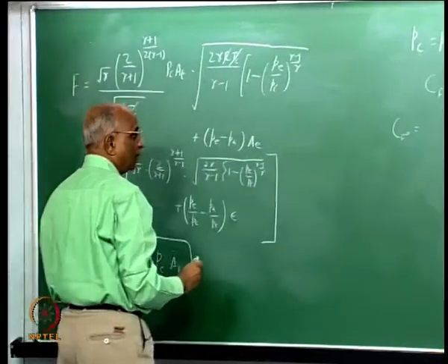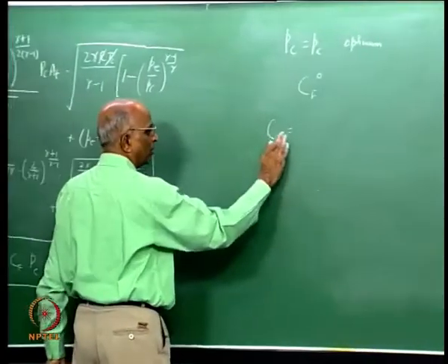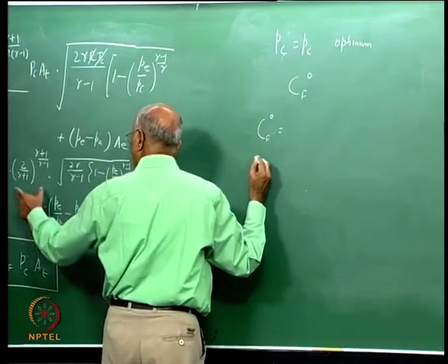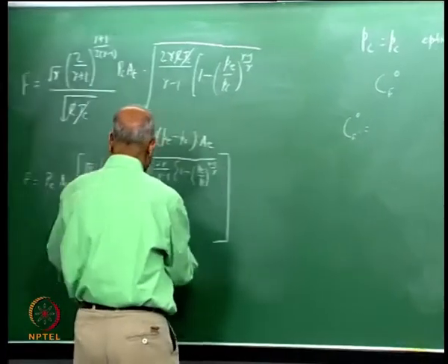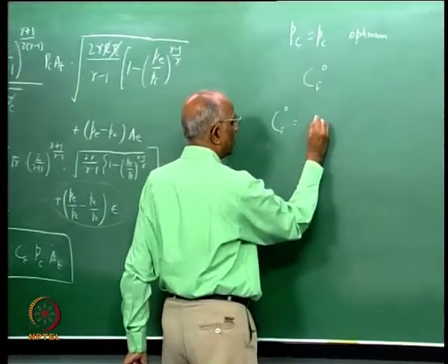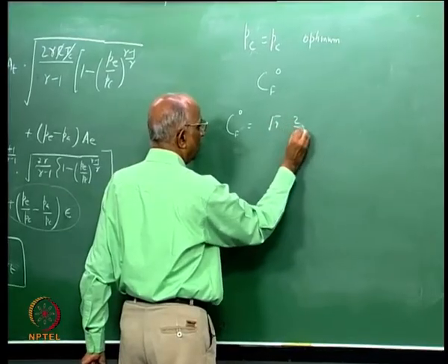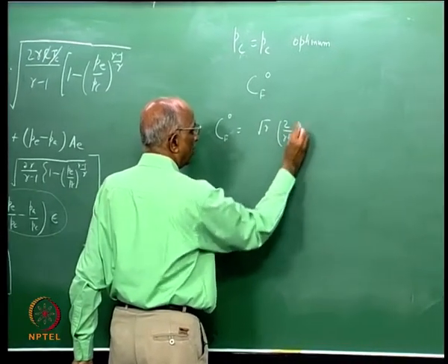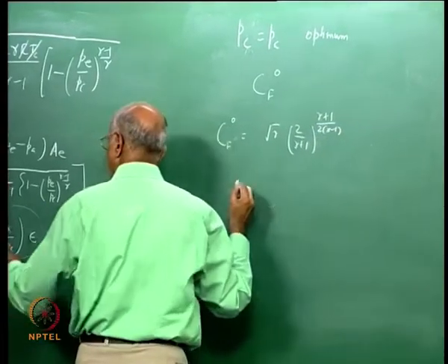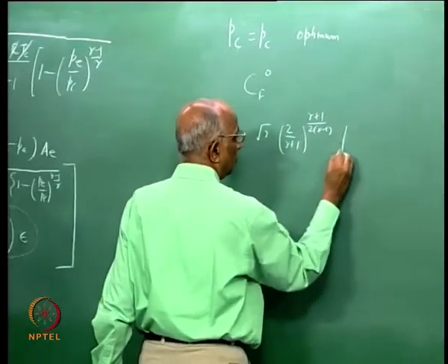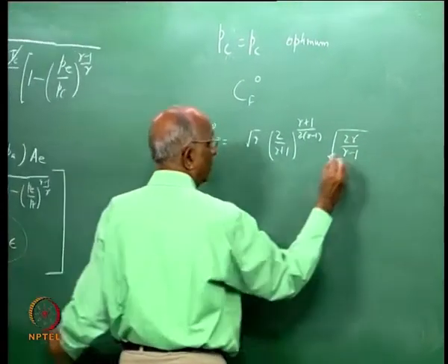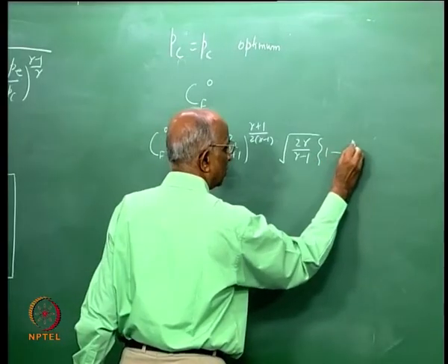I just write the whole expression other than this particular term which goes to 0, and I get Cf0 equal to under root gamma (2 over gamma plus 1) divided by (2 gamma minus 1) into under root 2 gamma by gamma minus 1 into 1 minus Pe by Pc...